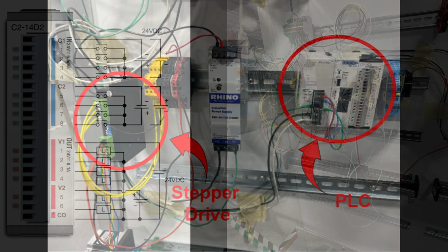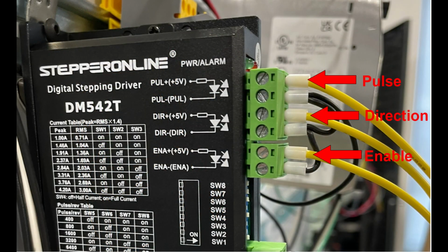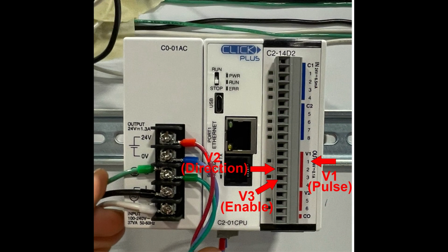For the connections between the driver and the PLC, I used sourcing logic, as the documentation stated that the driver didn't have a preference, but the PLC did, which was sourcing. The connections involved three wires, one for the direction, one for pulse, and the last for the enable to the driver. The other end of these wires were connected to the V1, V2, and V3 on the PLC outputs.